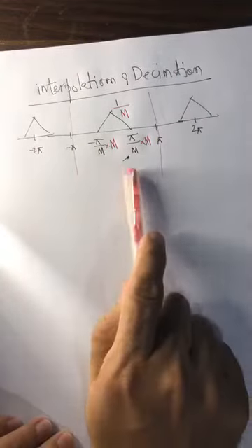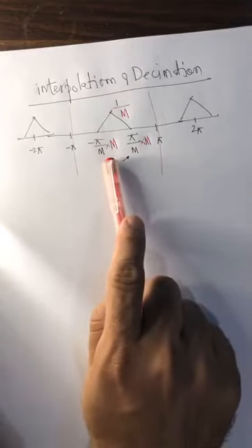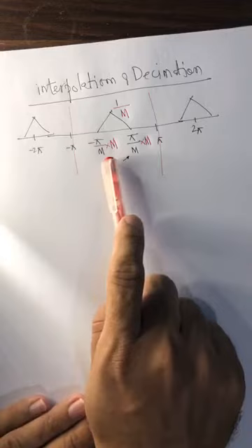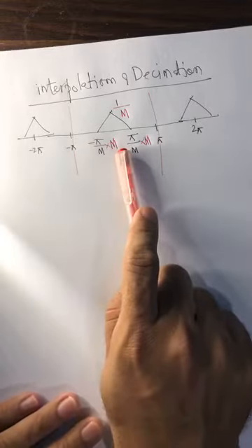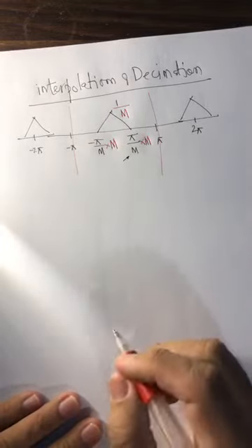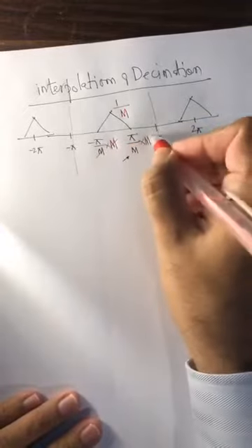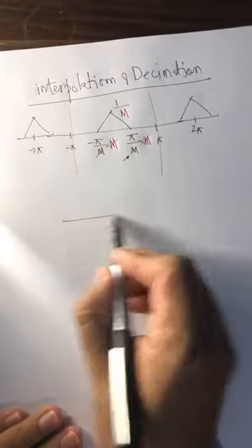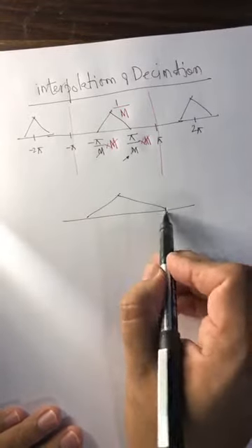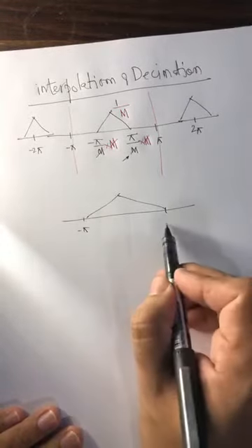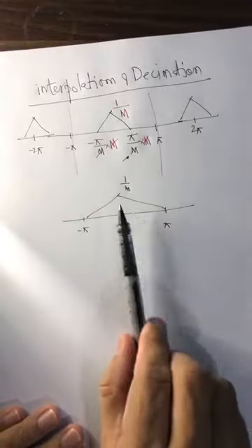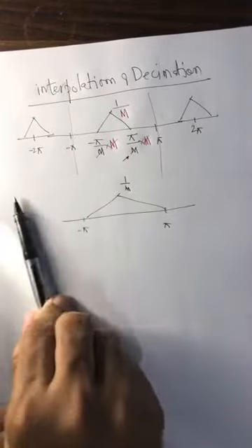From minus pi to pi, you do this operation: you multiply the spectrum by M. So if M is equal to 2, with 2, and M is equal to 3, with 3. Once you do this, M cancels with M, and you have a full-blown spectrum that goes from minus pi to pi, and the amplitude is 1 over M. Then you make copies of this spectrum at every 2 pi, minus 2 pi.